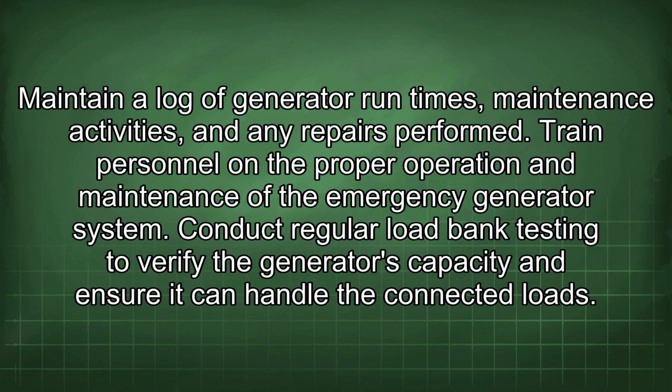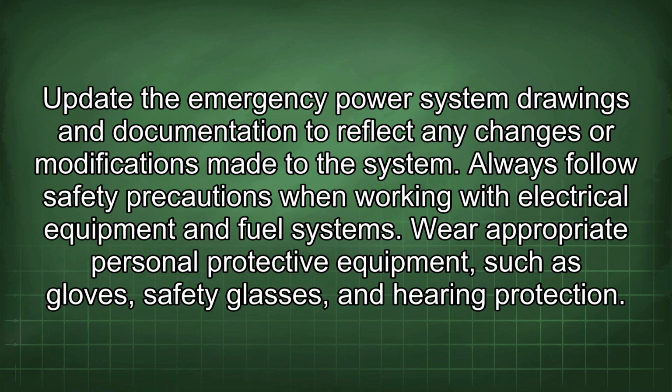Train personnel on the proper operation and maintenance of the emergency generator system. Conduct regular load bank testing to verify the generator's capacity and ensure it can handle the connected loads. Update the emergency power system drawings and documentation to reflect any changes or modifications made to the system. Always follow safety precautions when working with electrical equipment and fuel systems.